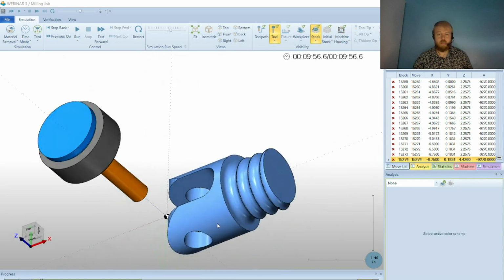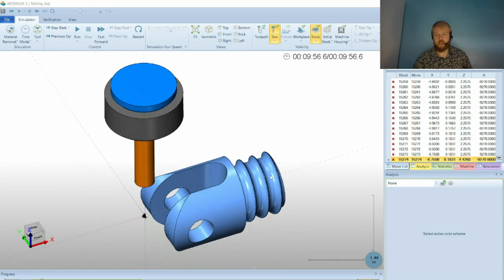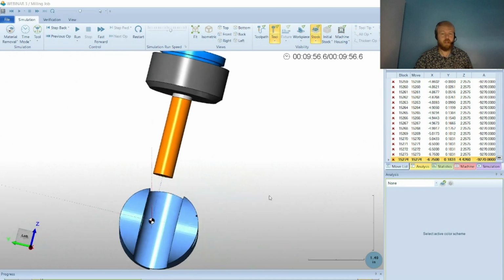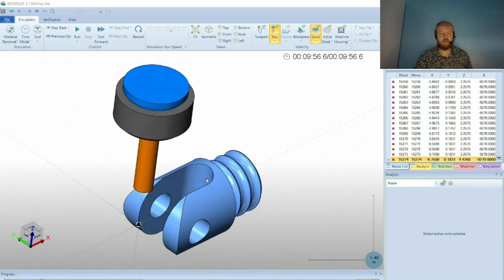You may be able to use a different tool or toolpath for the threading here, maybe with a threading tool. But if we were using a ball end mill for it, that's probably the best way to go about it, would be using one of these 4-axis toolpaths to follow along the surfaces for it and set a specific depth of cut that you wanted. And it'll have a limited amount of passes for you, so that you don't have to take too much time with your toolpath and things like that.